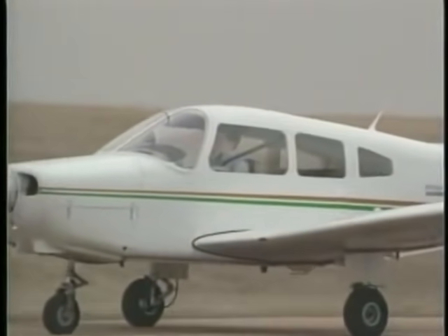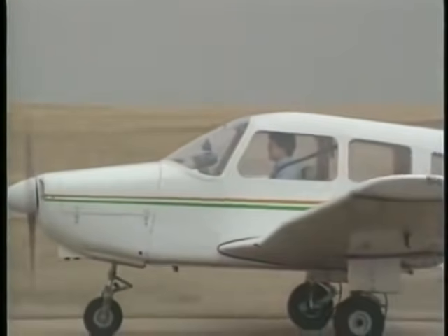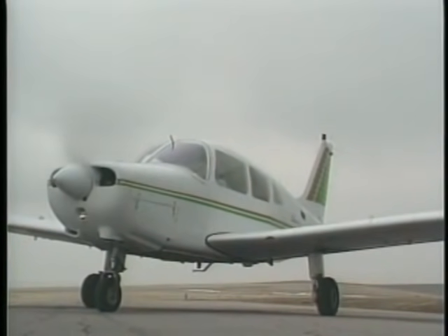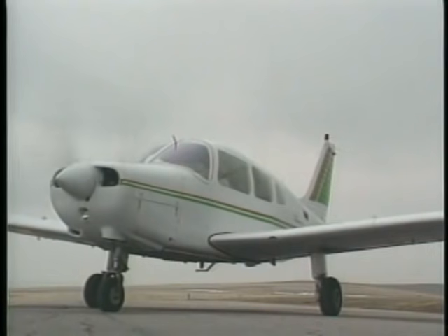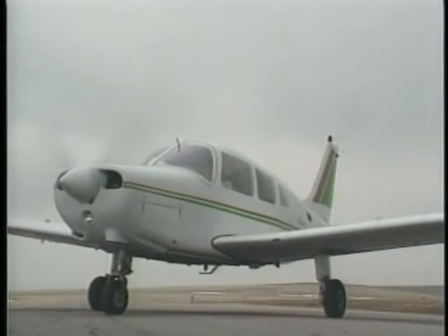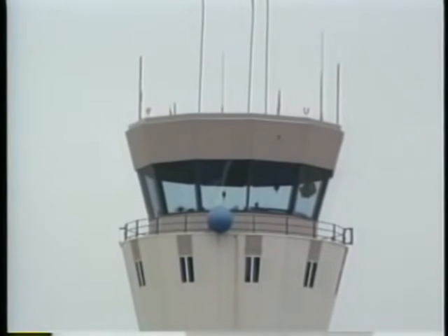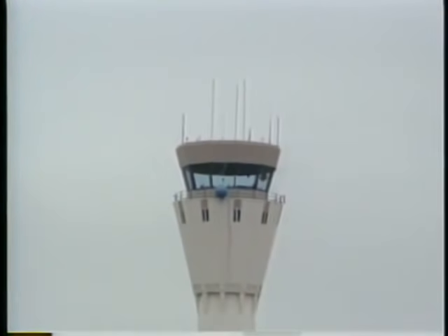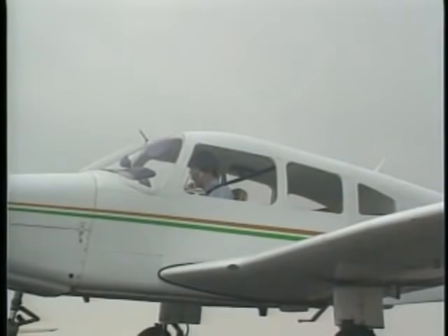Warrior 312, clearance. Cincinnati ground, Warrior 312, stand by. Cincinnati ground, Warrior 312, ready to copy. Warrior 81312 is cleared to the Greater Pittsburgh Airport, Lunken 1 departure, Appleton transition, then as filed. Maintain 2,500, expect 10,000 10 minutes after departure. Contact departure control on 124.5, squawk 5415. Roger, Warrior 81312 is cleared to the Greater Pittsburgh Airport, Lunken 1 departure, Appleton transition, then as filed. Maintain 2,500.